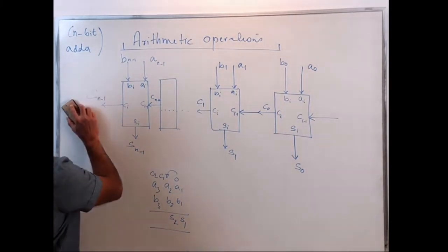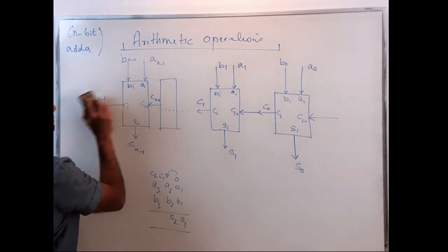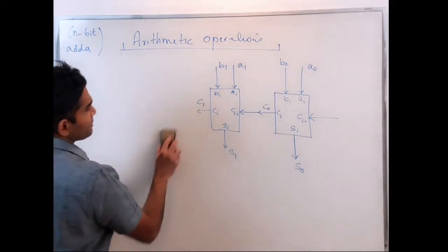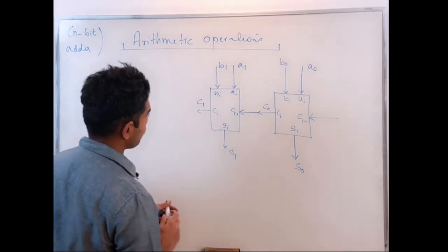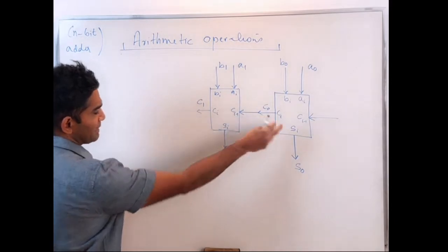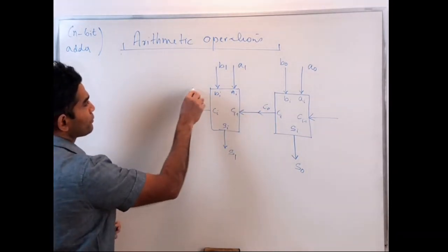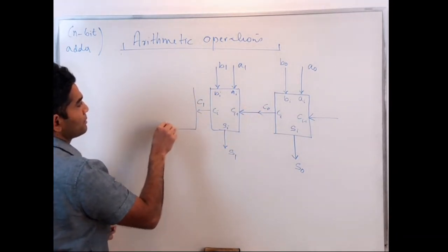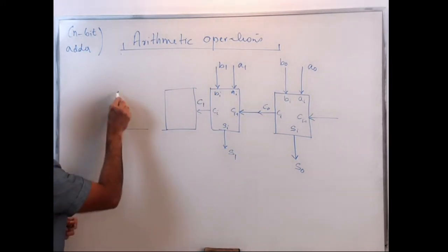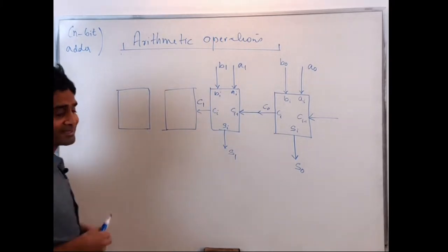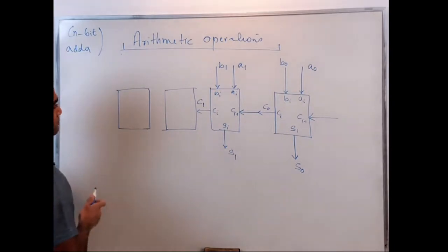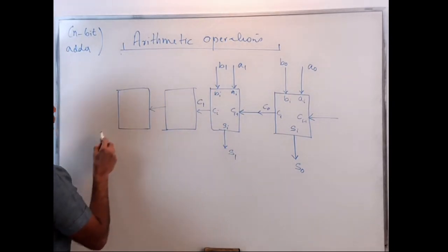Okay, so let's start simply. Let's design a 4-bit adder. Again, it's the same thing. For a 4-bit adder, I need 4 modules of this, the same thing copied 4 times. So this is a 4-bit adder. And now I know how to extend it simply. All I have to do is copy and paste multiple of those to get whatever adder size you need.